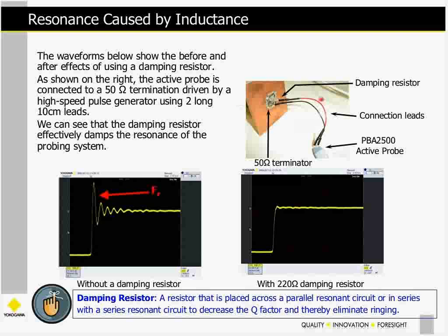And you can see that these damping resistors actually make your measurements a little bit easier. They give you longer leads, which is exactly what I've been telling you not to do. But sometimes you need longer leads. And in fact, in this measurement, I've used the damping resistor plus some little segments of wire. And this keeps the stress off of the test engineer, but certainly off of the probe as well. So the probe there is laying casually and taking this measurement.